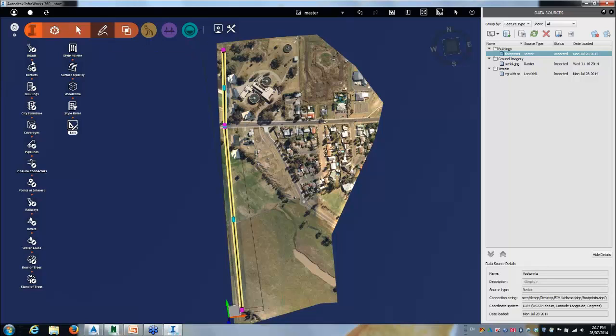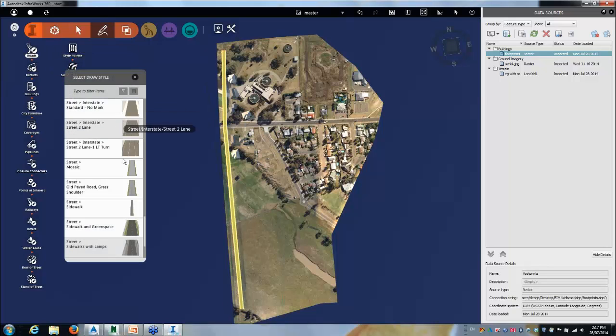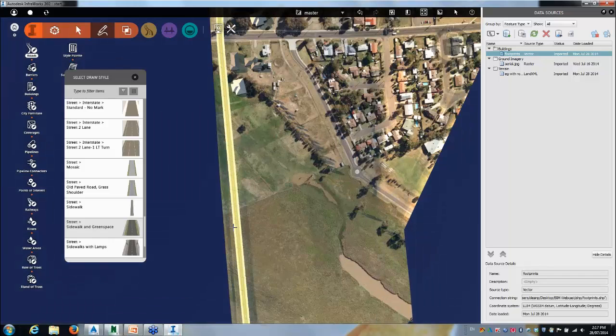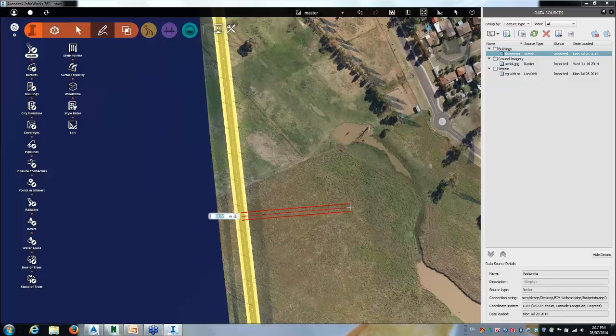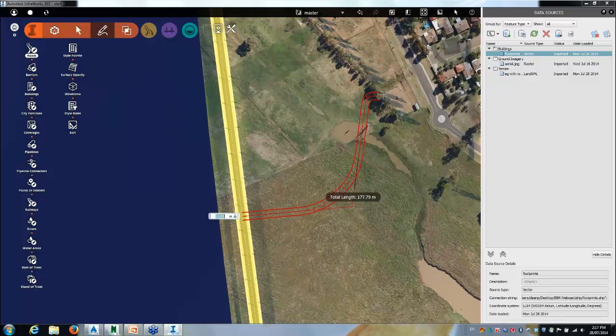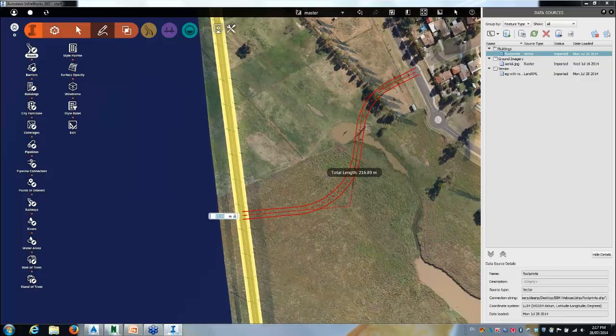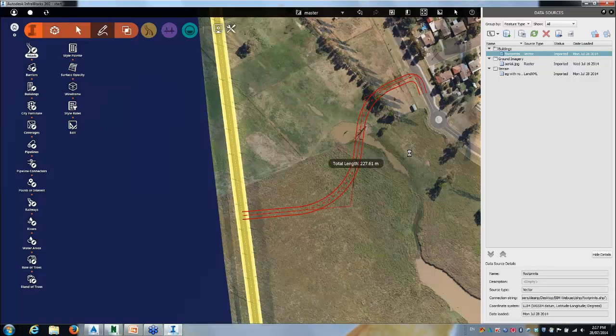In the standard version you do it this way, click on design and then roads, and then choose. You can see the styles are very similar. Let's grab one the style, shall we say, and they'll snap together with the 360 roads just fine. But you don't get much of an option over what the radii are and things for the new roads you're making when you do it with the standard version.